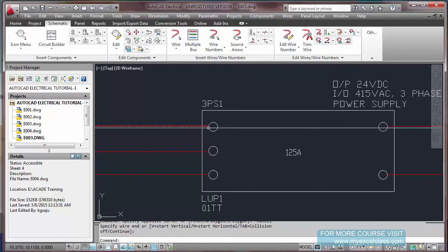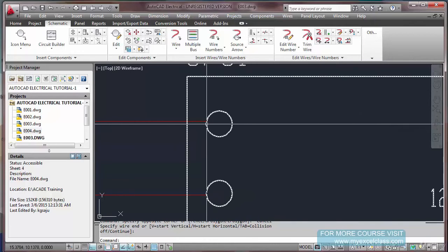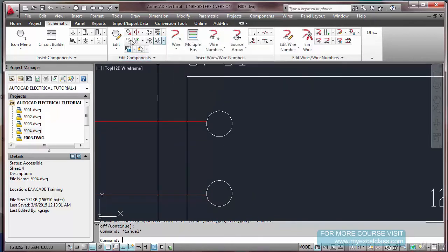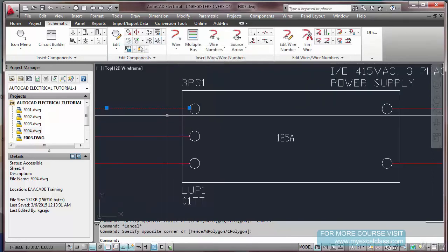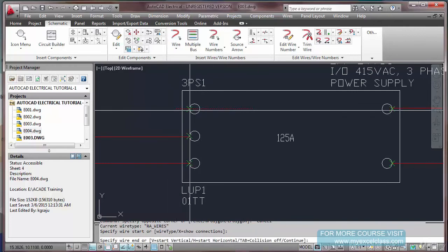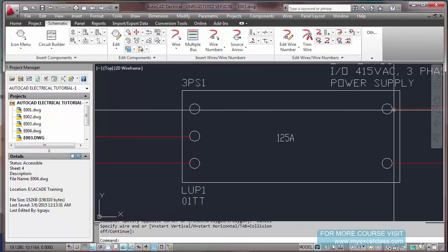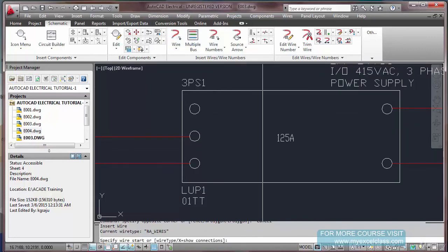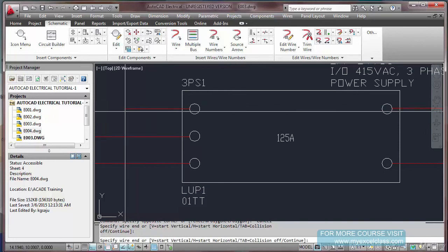See, this is the point where we inserted a pinpoint left. If I draw a wire from right to left, from here to here, see this green cross, that is what we inserted while making this block terminal number. You remember that for these three left-hand side terminals we use left, and for those on the right we use right. So if I connect a wire from this side to this side, see,